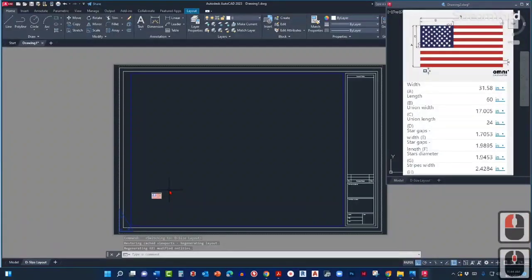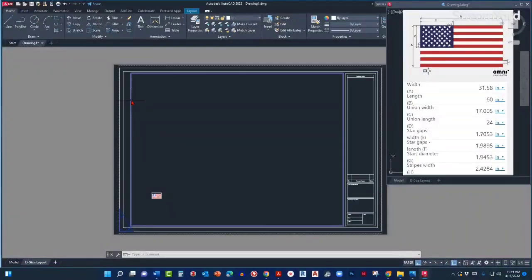And over here, what I want to introduce is the viewport command, because that's what we're going to need to set the size. The viewport is right here. That's a viewport, and it's a way to see through to objects from model space.